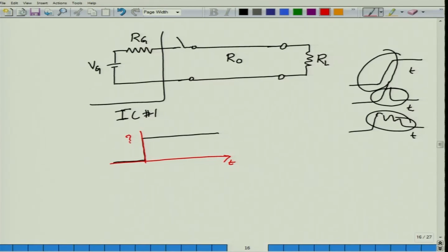So, this voltage is a change in the voltage, and this is the switch that would be closed at t equal to 0. What we want to do is to understand what happens when the switch is closed, so that this voltage is now connected to the transmission line. Before connecting this voltage, we will assume that the transmission line is uncharged, that is, there were no remaining charges, and therefore this transmission line was simply two wires which were completely inactive.